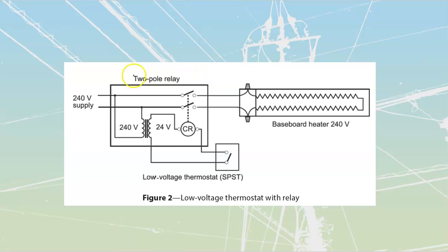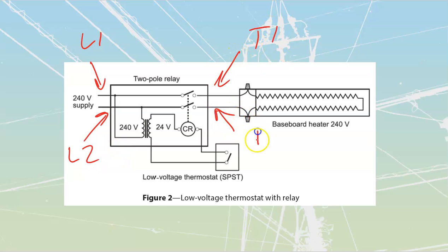This is seen as just a control board. It can sometimes be built into the unit itself. Other times it is just a separate thing where we have terminals. Over here we would see line 1 and line 2 terminals, and on the other side we would see T1 and T2 terminals. That indicates the load. L's are lines, T's are loads when it comes to control devices.